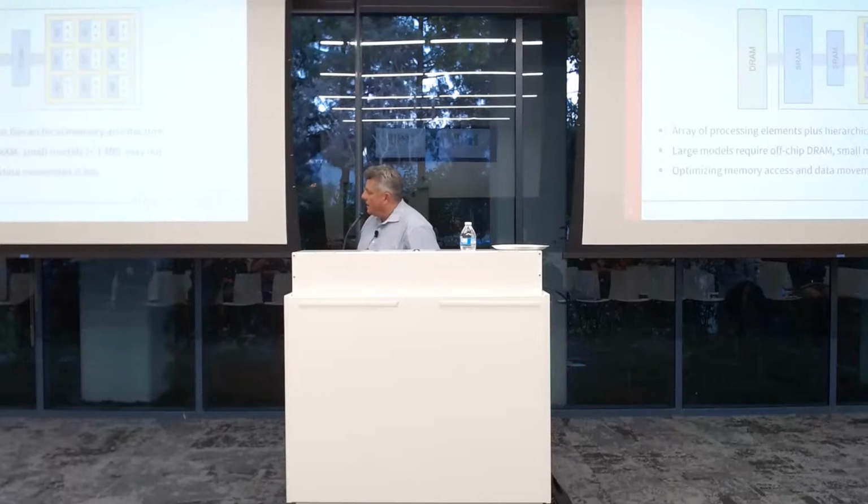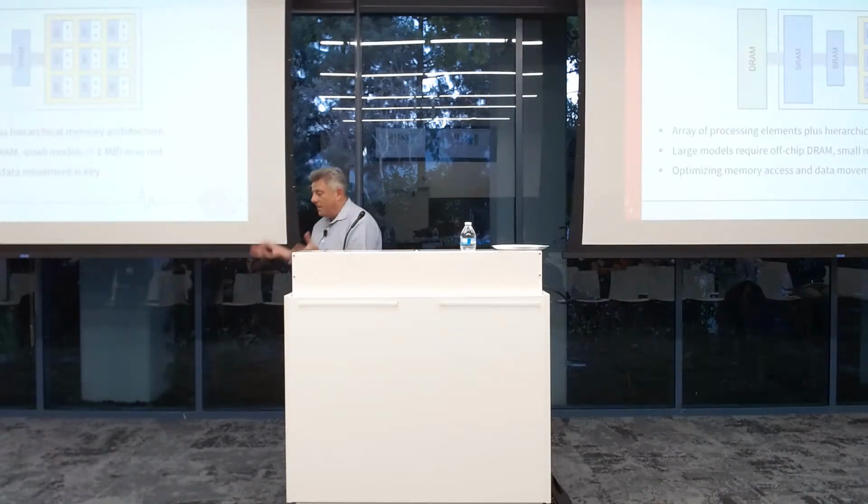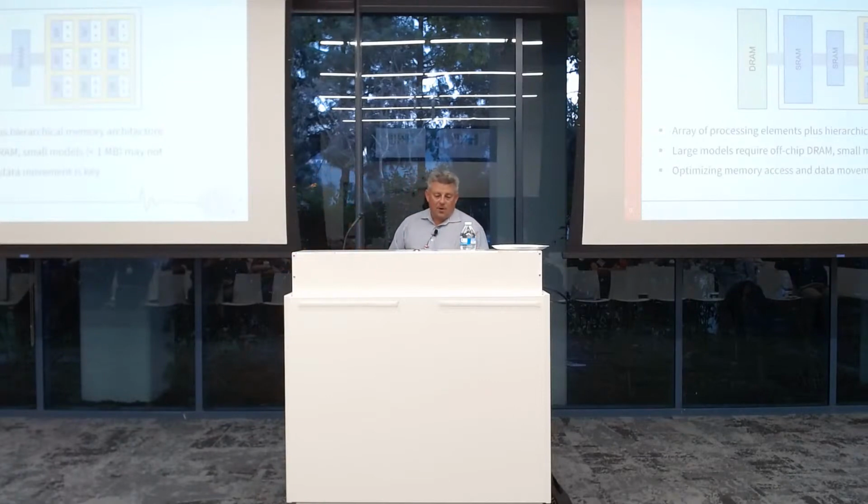So whether tinyML will actually need DRAM or not really depends on our friends that do model compression and stuff like this. If we actually down the road find a way to compress some really high-performing algorithms into, say, less than a megabyte for a large variety of operations, maybe we don't even need DRAM. But the reality is that for many high-performing algorithms, you may actually still need DRAM nowadays.